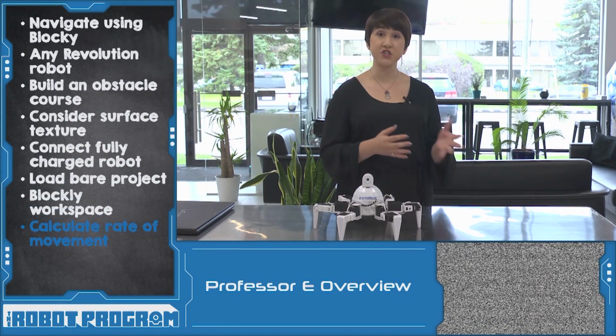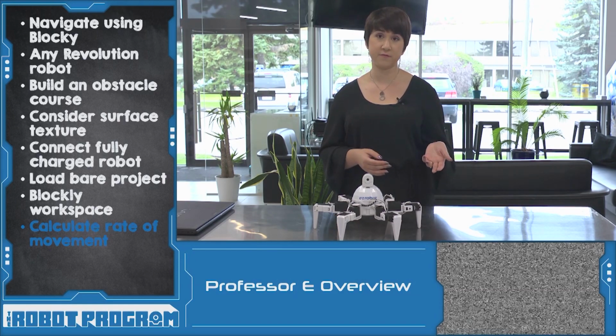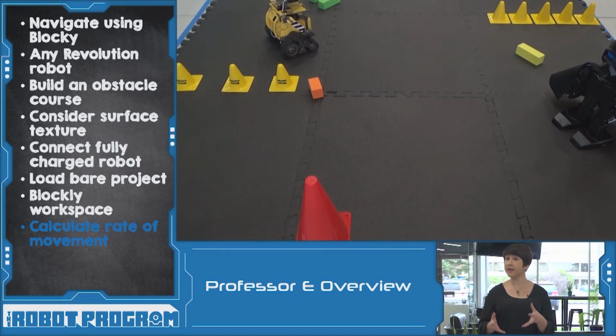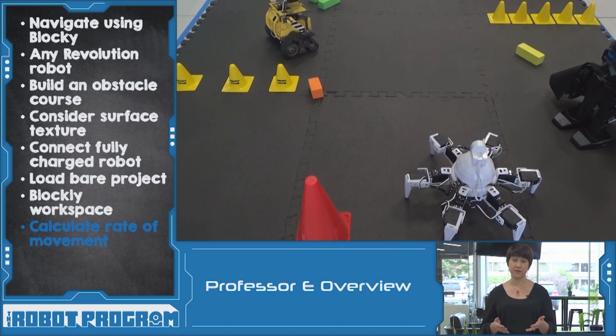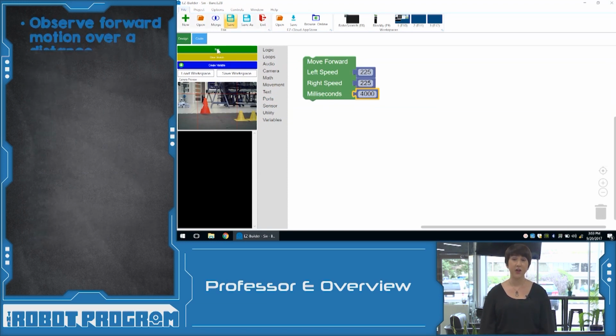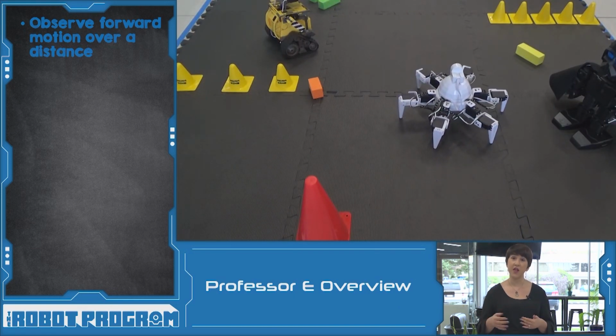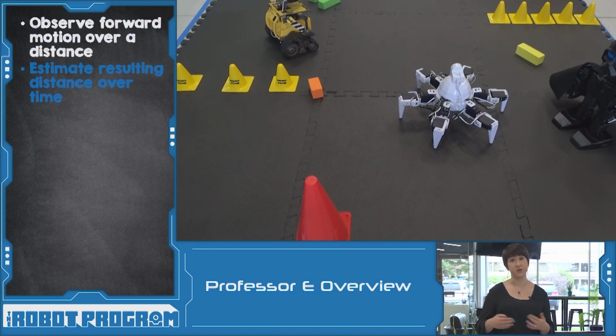Before we could create the navigation program, we had to understand how our robot moves when it's moving forward, backwards, right, or left. Place your robot in an area without any obstacles and test the movement forward. Choose a speed depending on how fast you want your robot to navigate the obstacle course. I wanted 6 to move pretty quickly, so I chose 225 as my speed setting, almost near the maximum speed for 6. Choose a time, maybe 2 seconds, maybe 5 seconds, and then click the green Start button to execute the code. You'll then get a chance to see how far 6 moves in that 2 or 5 seconds that you chose. This gives you a rate of movement, distance over time.